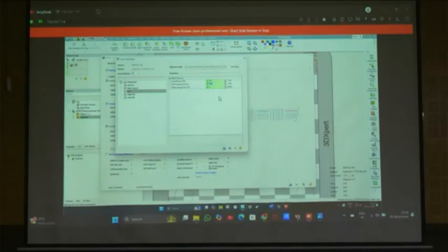Octet is better because it is stretching dominated. Always remember this lattice testing terminology: stretching dominated structures have better stiffness compared to bending dominated lattice structures. Most of the TPMS are bending dominated. For strut based lattices, whether they are stretching or bending dominated depends on the Maxwell's number. There is a formula to calculate the Maxwell number.